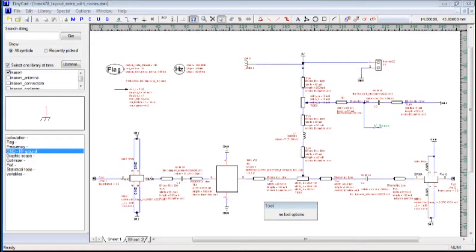And then with that, I can map this 1st terminal to port 1 of my little primitive file, dynamic file, of this inductance. Terminal 2 gets mapped to port 2, and then the 4 pins that are just the DC grounding for the RF connector, those are zeroed out because they're not actually part of the simulation.